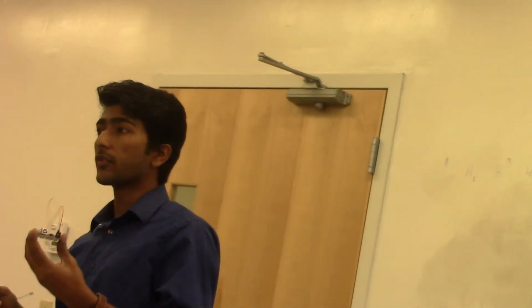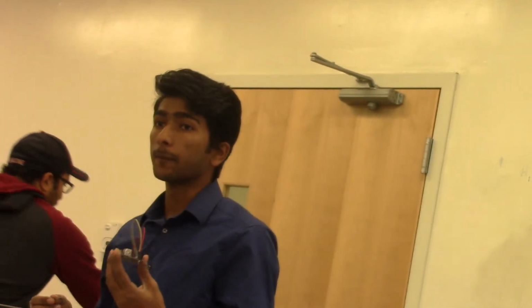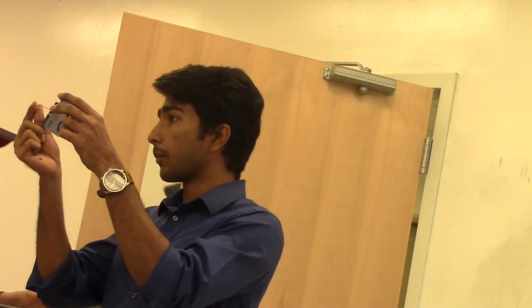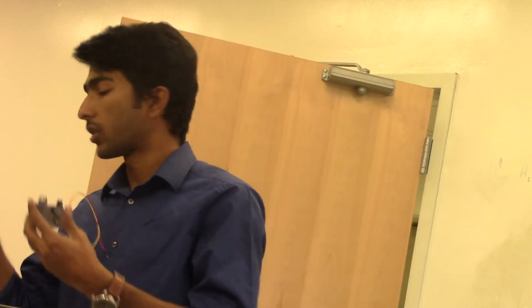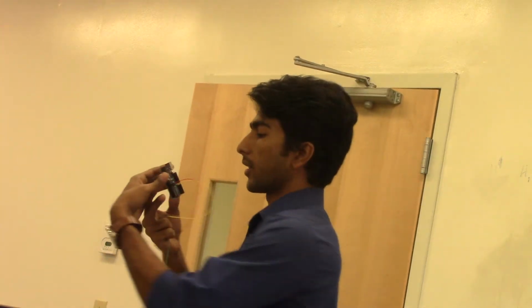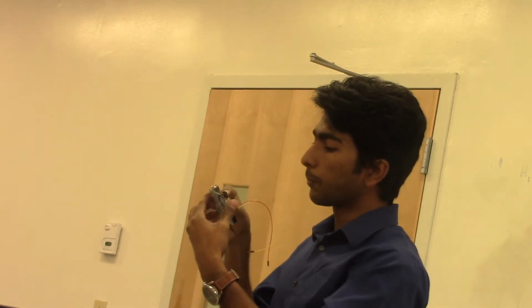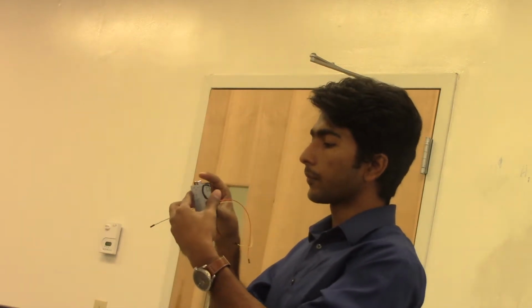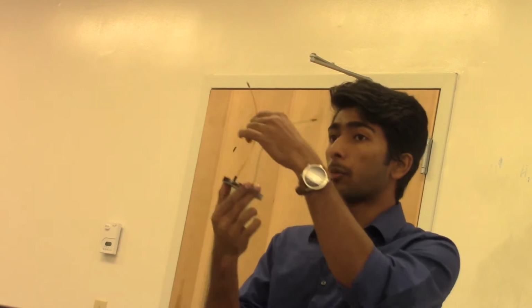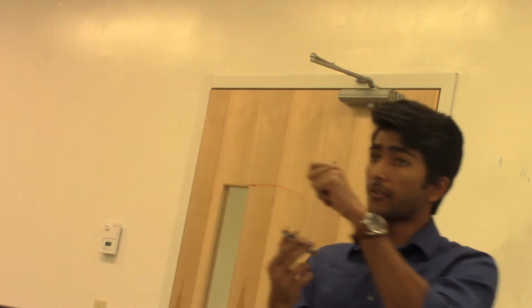And remember that I told you that we need to use a pulse width modulation pin in order to send a signal. So these are the power cables, and we need one more signal cable, which is on your, let's say, if I hold it this way, on your left set of pins. So I can use pin number 13 in this case. So now I have 3 wires properly connected. I have the power, I have the ground, and I have the signal.